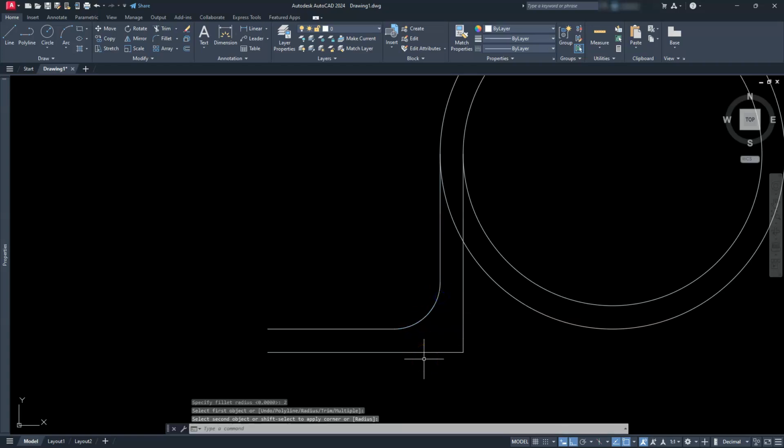Now if I continue that same method that most people make a mistake on, they'll go fillet, and they'll go, okay, yeah, that's the same radius, and it's 2 because it's pointing into it. And if I do this fillet, you're going to see that it looks a little bit bumped out here. So that's not actually correct, and it doesn't really look great in my opinion. I'm going to go ahead and delete that.